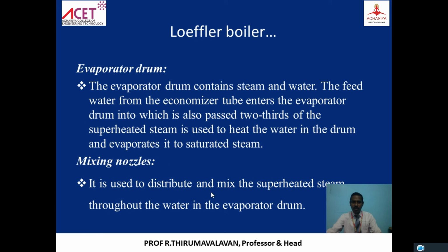Right. The next one is the evaporator drum. Like a Lamont boiler, the Loeffler boiler also has an evaporator drum. See, the feed water from the economizer tubes enters the evaporator drum, where 2/3 of the superheated steam is used to heat the water. 2/3 of the steam is taken back after the superheating, and 1/3 will go to the turbine. 2/3 is taken for the conversion of the feed water into wet steam.